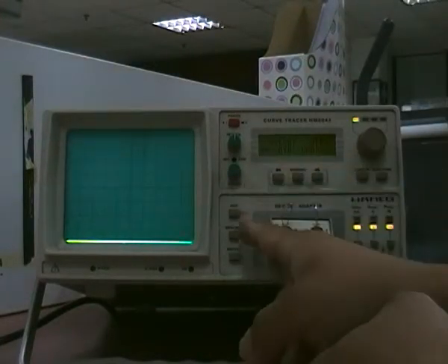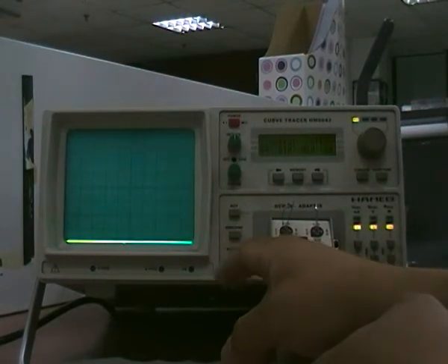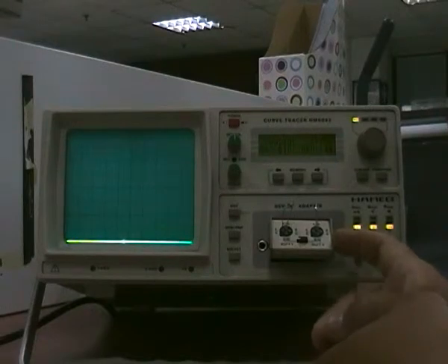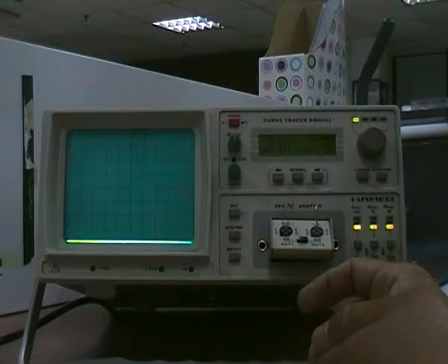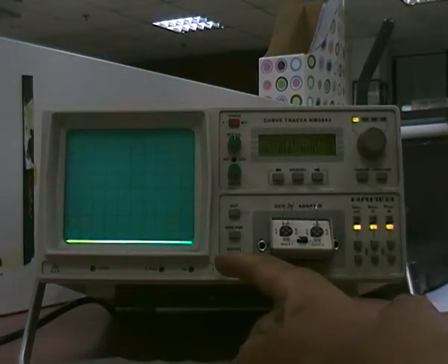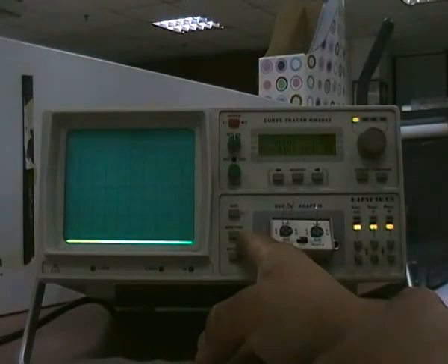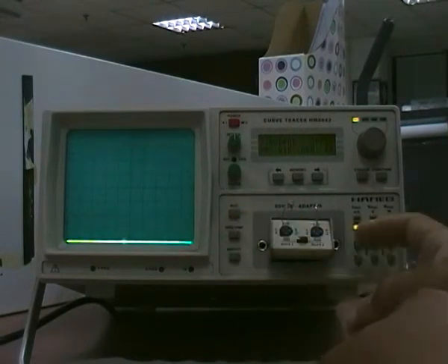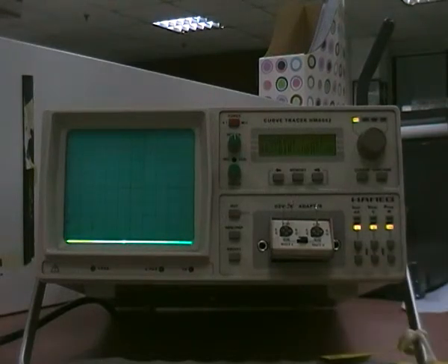When you switch on the curve tracer, the first thing you're going to get is a welcome screen, and then you have to set the device that you want to measure. This is a device adapter, so you can put two devices in one device adapter. You can choose either FET-based or silicon-based transistor. DUT is the device under test, which is put in this device adapter.